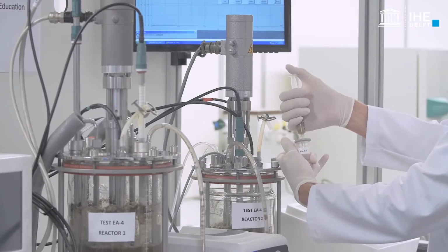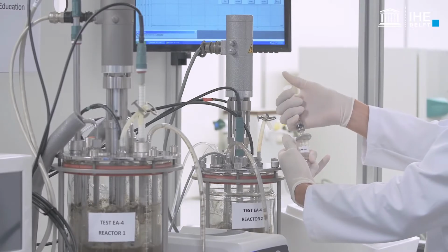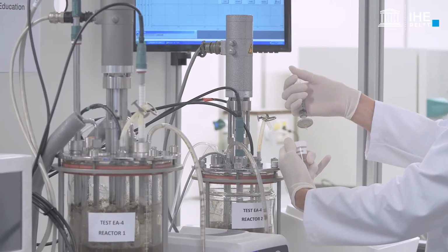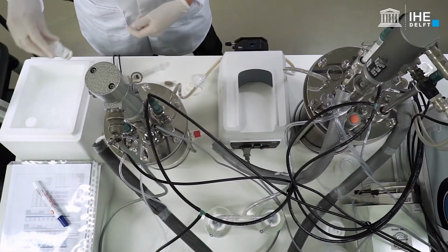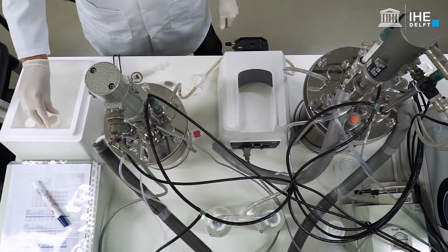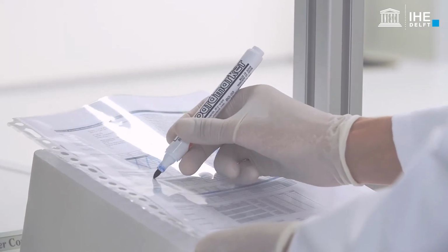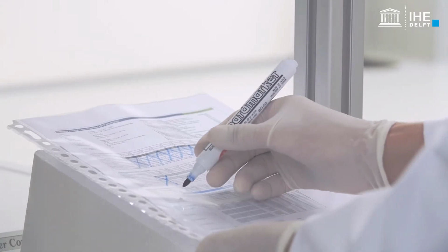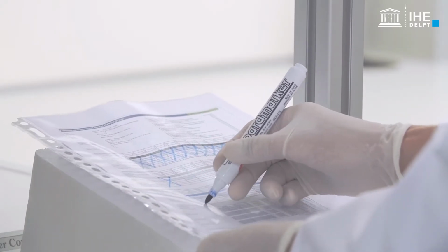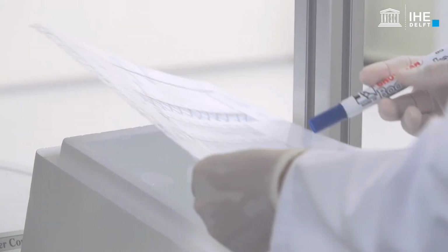As previously recommended, collect, filter, and place the sample in ice temporarily until it is properly stored, preserved, and analysed. Confirm that the required samples have been collected and mark it in the working sheet. Thereafter, continue with the simultaneous sampling of the anoxic phase in Reactor 1 and of the aerobic phase in Reactor 2 as planned and indicated in the working sheet.